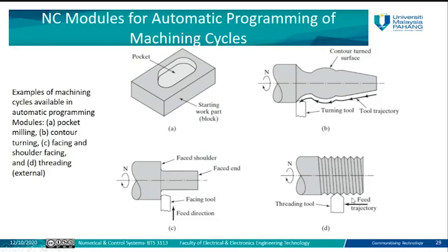So usually they have such add-on modules for the CNC machine. It is specific to performing such types of tasks. No need to create a program to ask the machine to go linear to this point, then go circular to this point, then again go circular to that point, then again linear, then return.